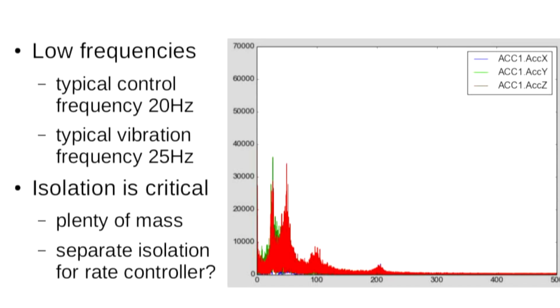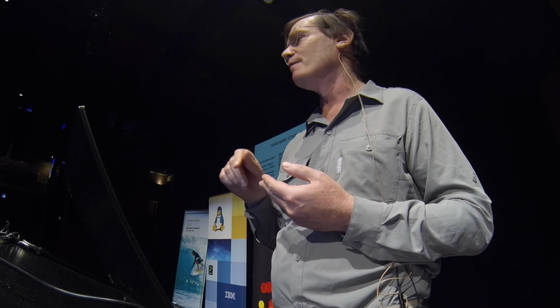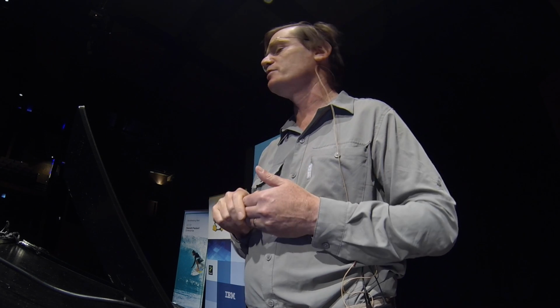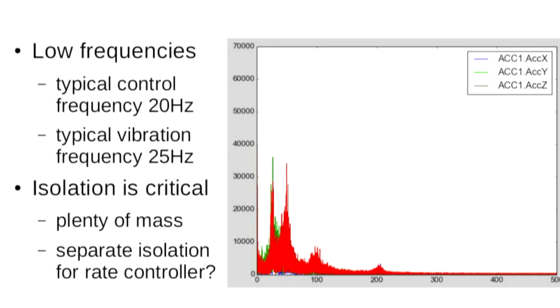So that's a lot of data it captures. And then we can run FFTs over that. So this is the result of an FFT of flying that JS90 that I showed you before, the close-up photo. And the interesting thing is where these peaks are. The horizontal axis here is in hertz, and if you can't see it, the first little number there says 100 hertz, so that first peak is around 23, 24 hertz or so.